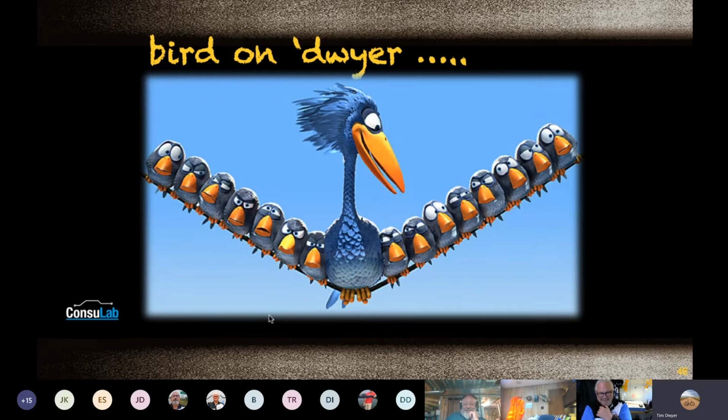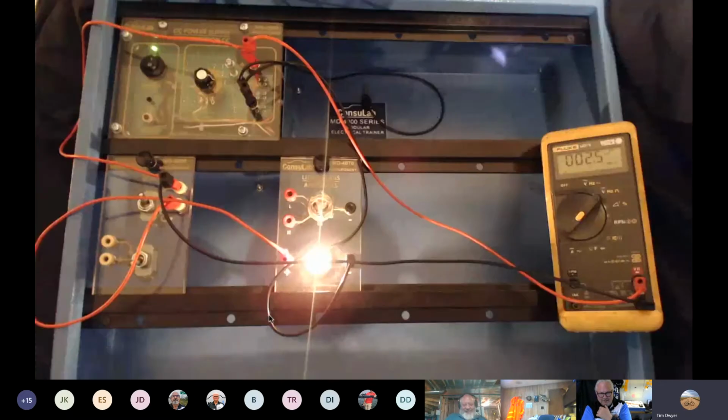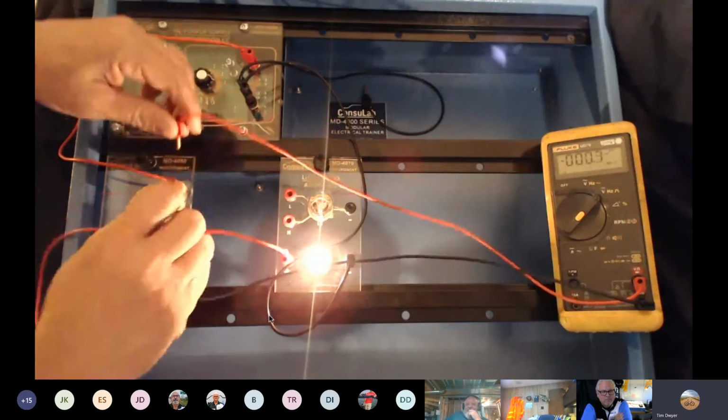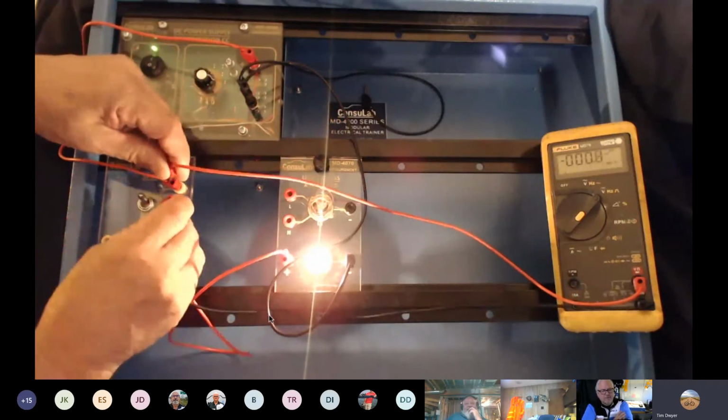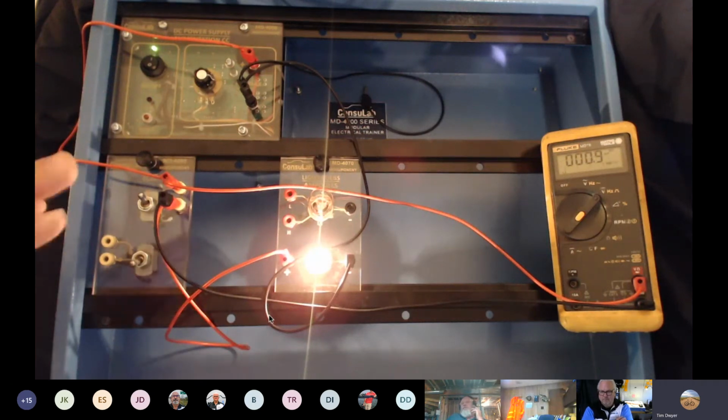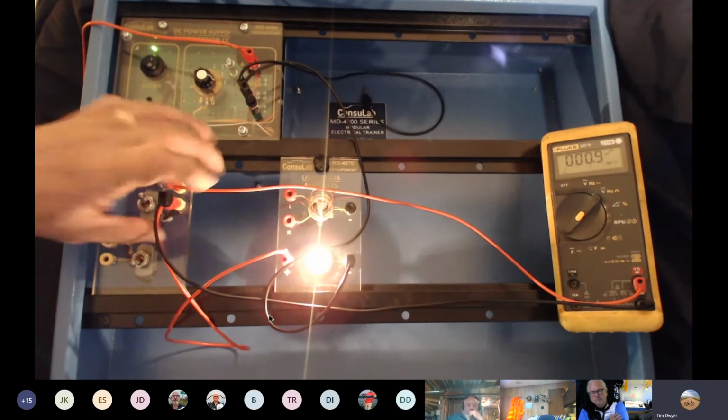But let's go and do what you're saying. I'm going to come down here. I'm going to pick this lead back up. I'm going to go to the next deal, which is really a functional test. I'm going to go over the switch, because switches can fail. They can get bad connections, contacts in them. There could be the plug into it. There could be a lot of reasons why a switch fails, and you can do a voltage drop over it.